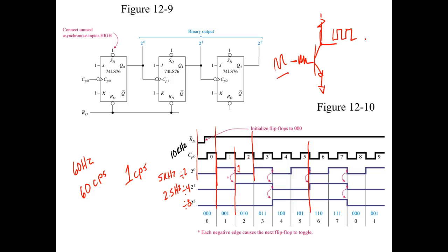And like I said, these computers right here, the I/O bus runs at 166 megahertz, but it's got to be in time with the high frequency bus, right? You understand that? So how do they make it in time? Well, they don't use 2 different clocks. They just take the clock that the processor's running at and divide it by something to get 166.